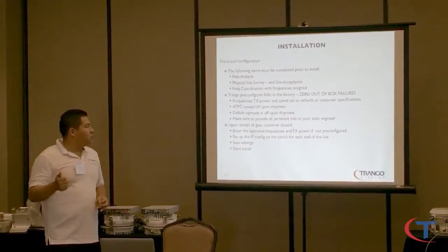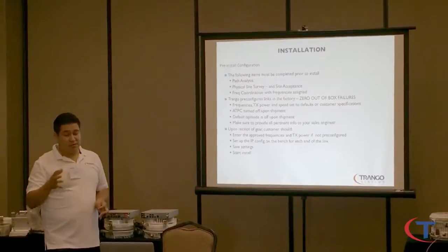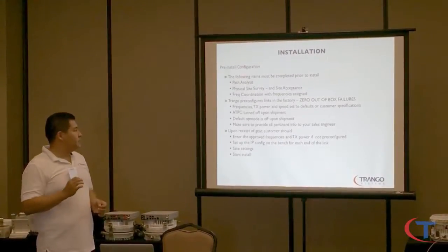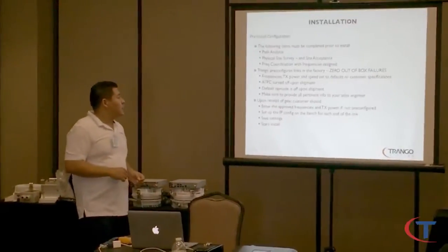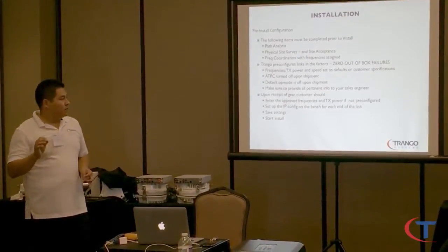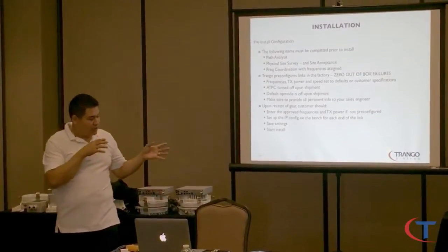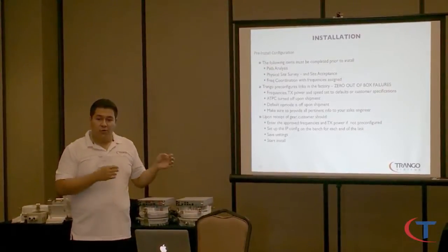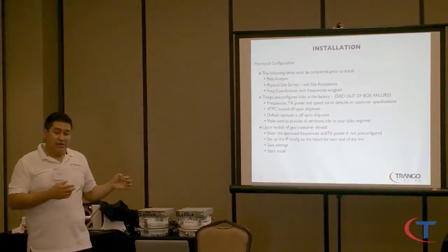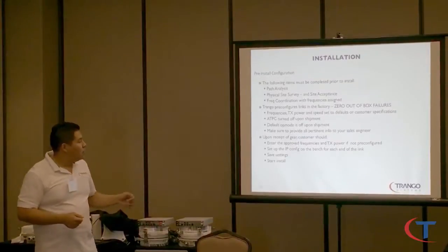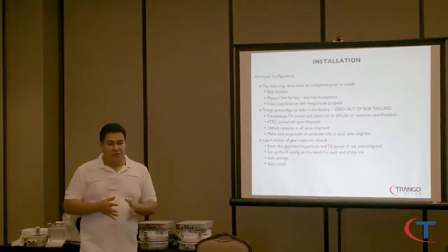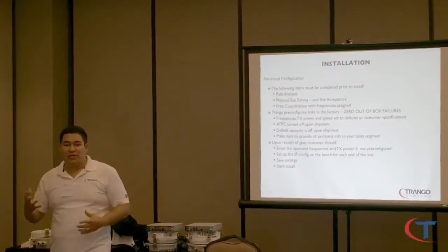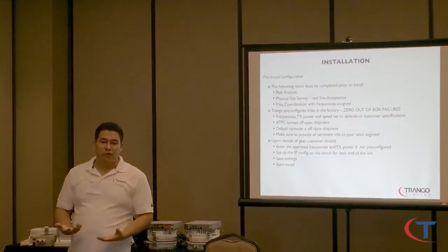Frequencies, TX power, speed are set to defaults or custom specification. ATPC is turned off upon shipment for the alignment process. Default output is off upon shipment, so you can actually connect the ODU. It's going to be ODU power off, but it's not going to transmit at all. Make sure to provide all current information to your sales engineer. So Ray must have all the information he needs to be able to help you build your link.